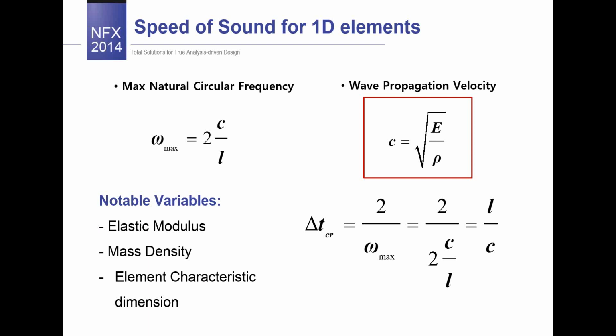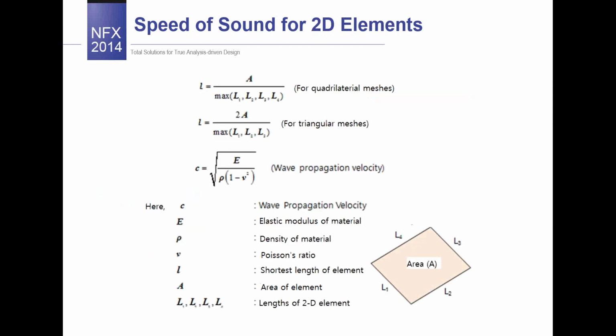And you're supposed to also take care every time you are generating meshes for explicit dynamic simulations to ensure that one or two small elements don't control the time step. But I will get back to this topic a little bit later.